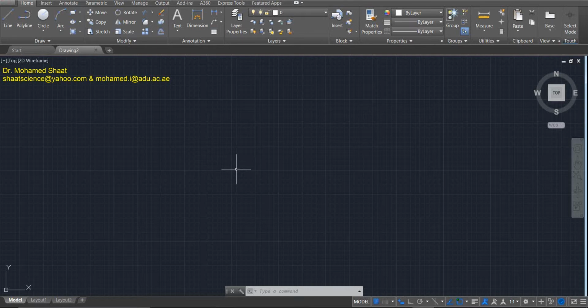We said that we have to achieve some contrast in the thickness between these different types of lines, so we can distinguish between, for example, the line that would be used for the dimension, or the line that would be used to represent a visible edge in the object. Also the line that would be used in representing the hidden edge in an object. So basically we do have different types of lines. As we said, we do have the visible solid line, we do have the dash line, we do have the center line. These are the main three types of line that would be used, but the continuous visible line, also the continuous line that would be used here is for dimensioning.